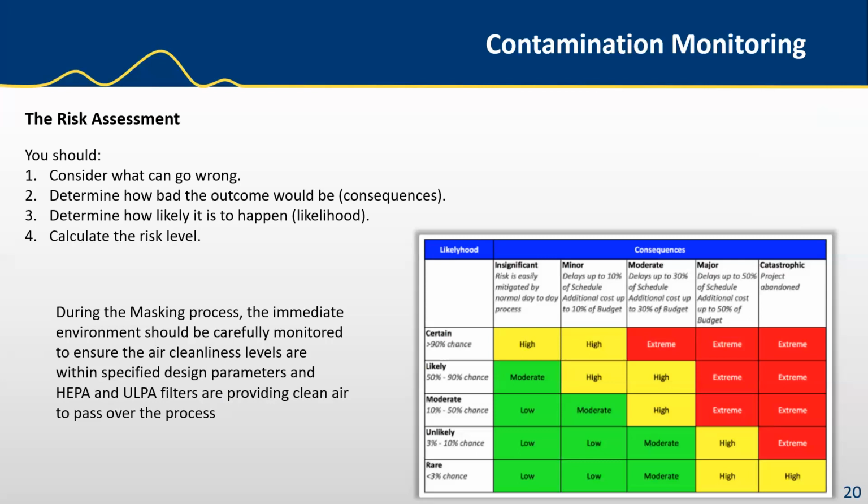During the etching processes, gases are introduced, and these gases also need some routine monitoring to ensure that they are not a source of contamination. Gas suppliers are required to provide certificates that indicate the purity of the gases. However, in a risk assessment, in-house monitoring of batches of gases should be undertaken to ensure the quality of the gas remains intact. So anything that you're introducing into the cleanroom, it is highly recommended that you monitor the cleanliness of that, if it's a gas or the air itself, and anywhere around the processes. Even the liquids that are used as well, as I mentioned, highly important.